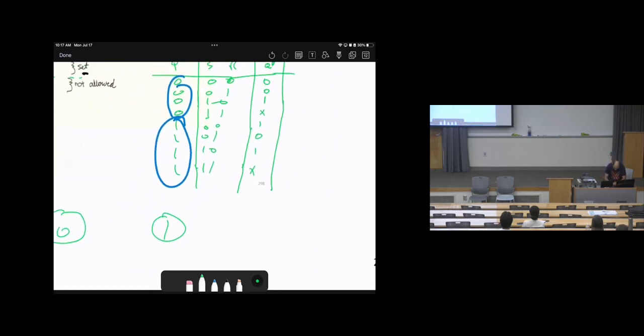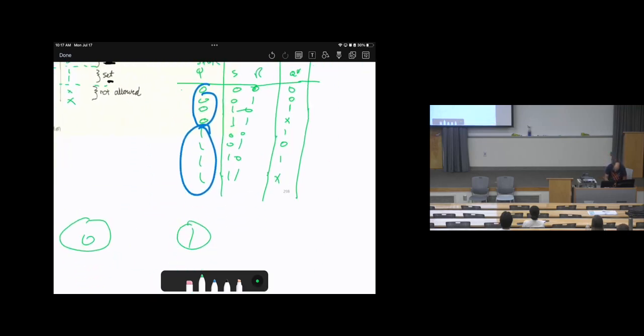So let's follow the first part. Look at 0: with 0,0, Q star will be 0. Therefore, the next state will be 0 if we have 0,0. Two inputs, so I wrote 0,0 close to each other, because this is two inputs. Then, with 0,1, it will be 0. So I can put a comma, 0,1, on the same arrow.